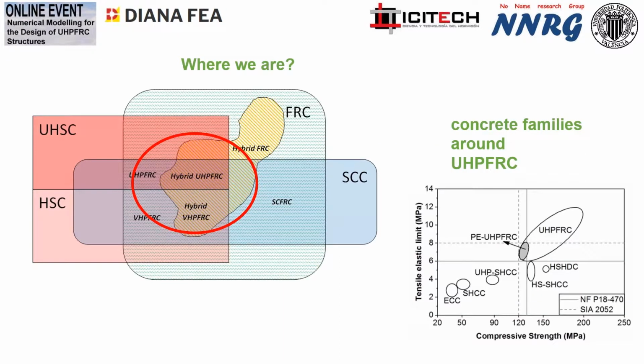We are thinking of ultra high performance concrete that combines most of the advantages of the new concretes of the last decades. It is self-compacting concrete, high performance concrete, high strength concrete, ultra high performance concrete, and always with a big amount of fibers. Everything joined will reach the properties that we will use as ultra high performance fiber reinforced concrete.